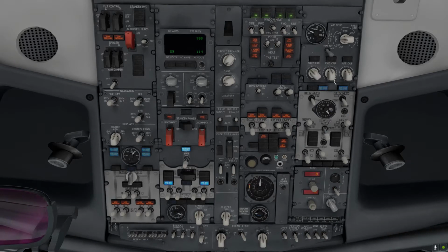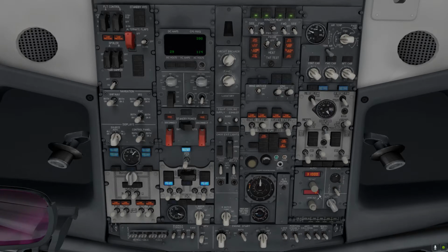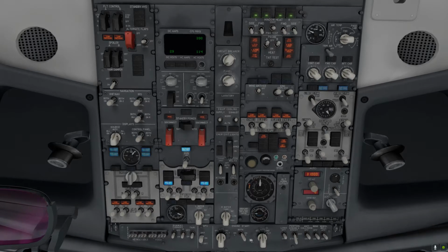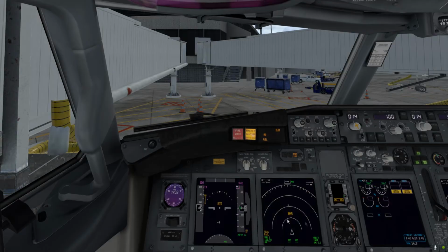First flight of the day, let's put them on around the 9 o'clock position, expecting flight level 310 in cruise, and landing altitude, the elevation of Miami, is about ground level, so I'm just taking it as 0. And engine start: the left igniter and steady light on. Yeah, that's pretty much it.